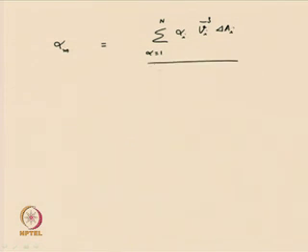So, I can now suggest the energy correction factor is of the following form: alpha equal to the sum from i equal to 1 to n of alpha I V I cubed del A I, divided by V m cubed A. This is the equation.